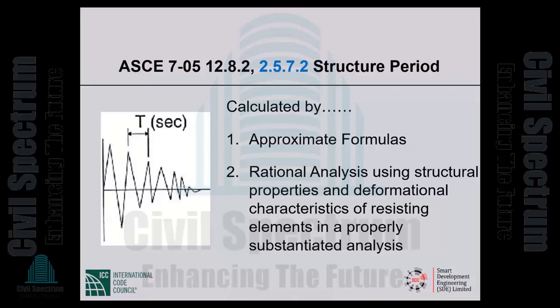For a concrete structure, by taking cracked section properties as low as we choose, we are in a position to calculate a period as long as we want it to be, which will then translate into a design base shear as low as you would like to design for. And that is not the idea behind the privilege of rational period computation. That is not supposed to be a license to lower the design base shear as much as you would like.